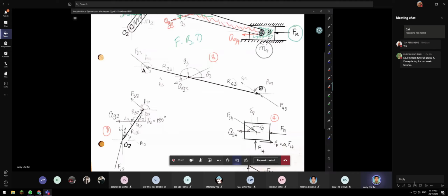The parameter is my acceleration, AG. This is the acceleration, so I must locate AG on the diagram, and I must also indicate the angle on the diagram here. Remember, the angle starts from the x-axis and goes all the way to the arrow of your acceleration.